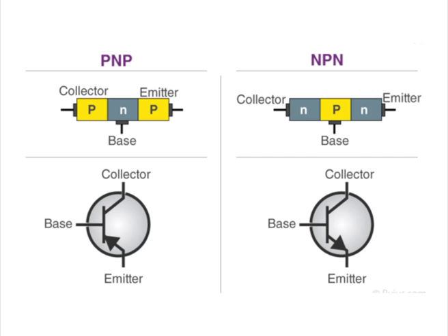Using this, now we will see further how the transistor looks. PNP transistor, NPN transistor. How to differentiate a PNP transistor from an NPN transistor? By the current flow direction. For a PNP transistor, the current direction is always inside. To remember: wherever the N terminal is, the current arrow points inside.